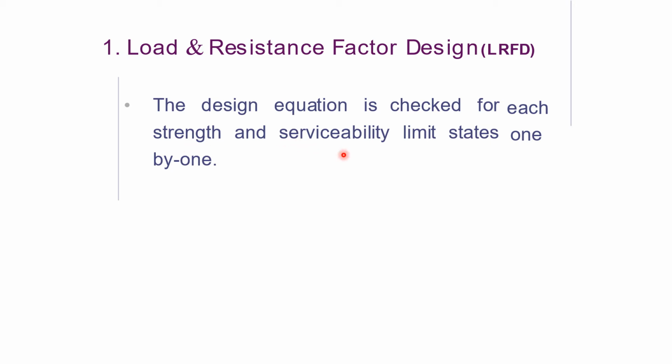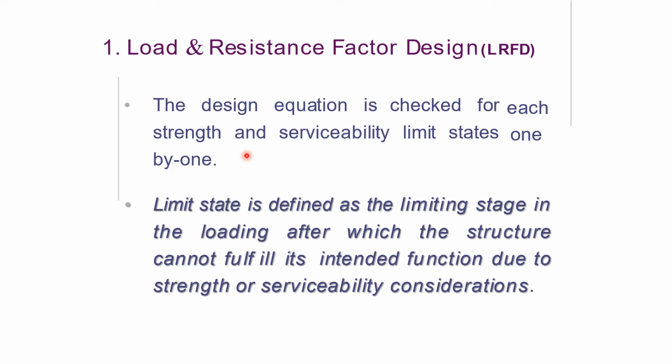And the serviceability limit state criterion is the deflection criterion. For example, if you have designed a steel beam, then that steel beam should not undergo large deflections. So to avoid these deflections, you also have to check against the serviceability limit to control the deflection. So these are two criteria.